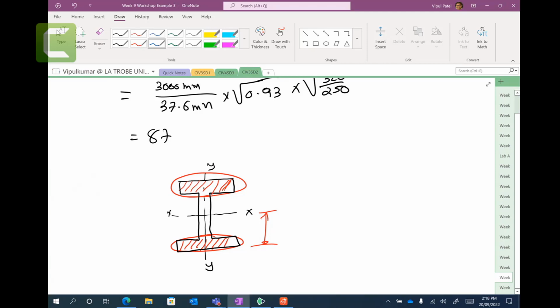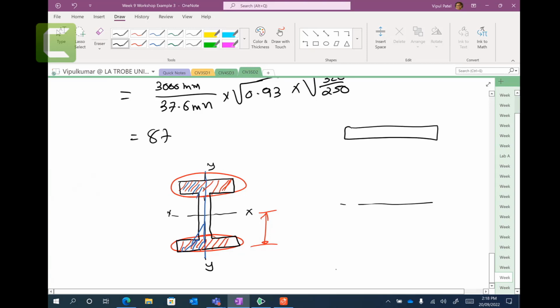So look at the other side. If I have this y-axis, look at the material distribution on the other side about this axis. This is how you get the moments. If you have an axis here and you put the material far from it, you have large I, moment of inertia, large resistance against bending.